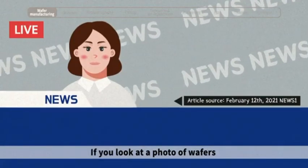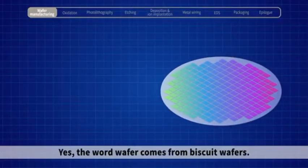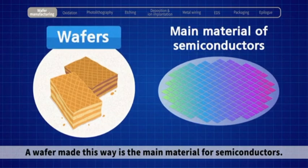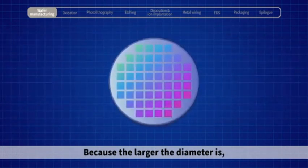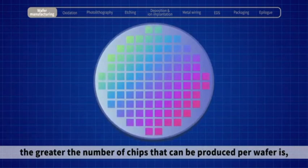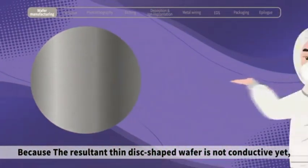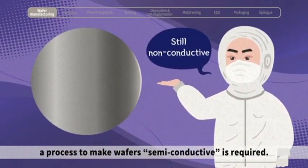If you look at a photo of wafers, you can see a grid pattern on the surface. Yes, the word wafer comes from biscuit wafers. A wafer made this way is the main material for semiconductors. Because the larger the diameter is, the greater the number of chips that can be produced per wafer is, the diameter of wafers is becoming larger. Because the resultant thin disc-shaped wafer is not conductive yet, a process to make wafers semiconductive is required.